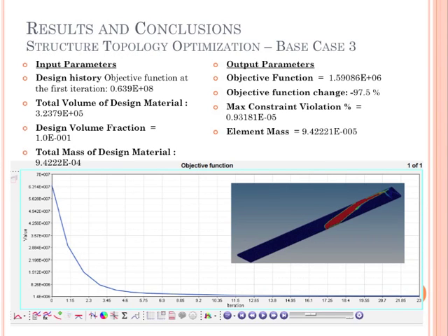Shown here are the results for base case 3. This produces a total mass of approximately 389 pounds for the structure. The mesh for this size was also run at about half of the mesh size of the previous 2 runs because the complexity of this model for the wing box shape, specifically the ribs and the cutouts in the model, made the meshing a little more difficult.